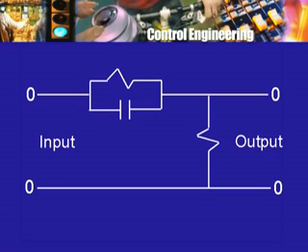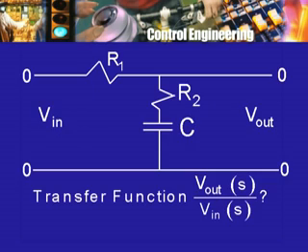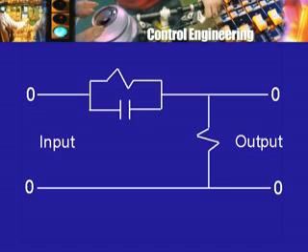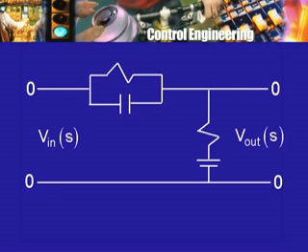This of course is going to be different from this case or from this case, and this again is where some kind of electrical engineering judgment you should build up. Here I should expect a first order kind of transfer function, that is maybe a pole or a 0 or a pair of poles and zeros, but first order, not second order. Similarly here, because there are two capacitors, I should expect a second order transfer function, that is the numerator may be of second order or denominator may be of second order or maybe both will be of second order. Find out which one it is.